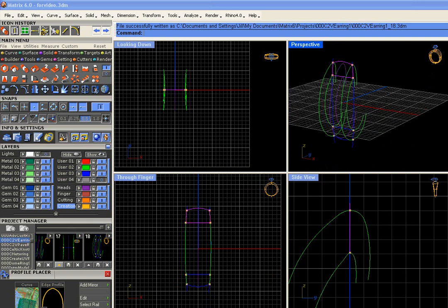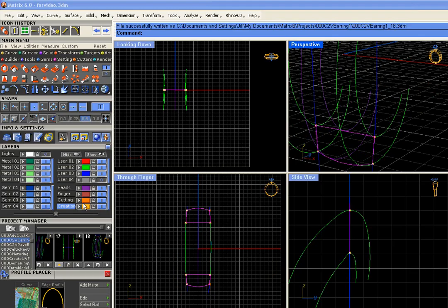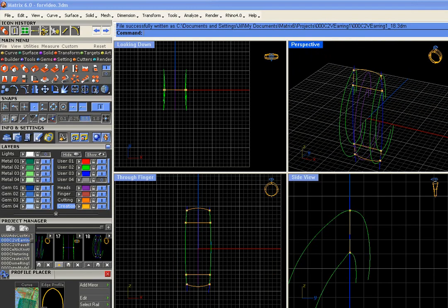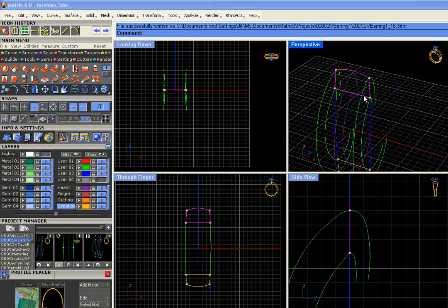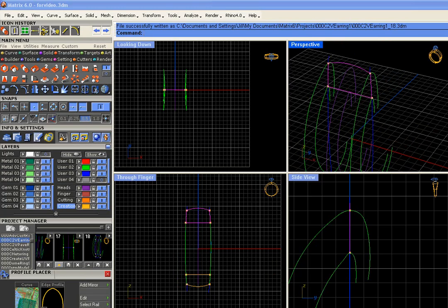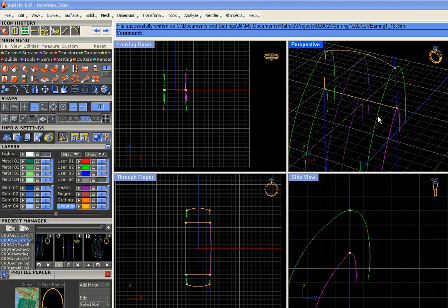Okay, we know that we have our profiles out here. Let's get them on a nice profile color. And then we're going to take these and we have to add them to the center rail. Okay, that's going to be the one they're associated with. And these four are going to be the rails for the four rail sweep.